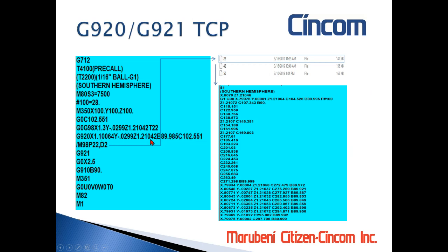Once you start programming this with CAM software, you will have a huge code. So I will read that subroutine from the SD card in this case, and this will be the subroutine. On the new controls, you cannot have any file extension, so it has to be blank. And then you will read the whole subroutine. This is just a snippet, but it's a huge code for just doing what I'm going to show soon.